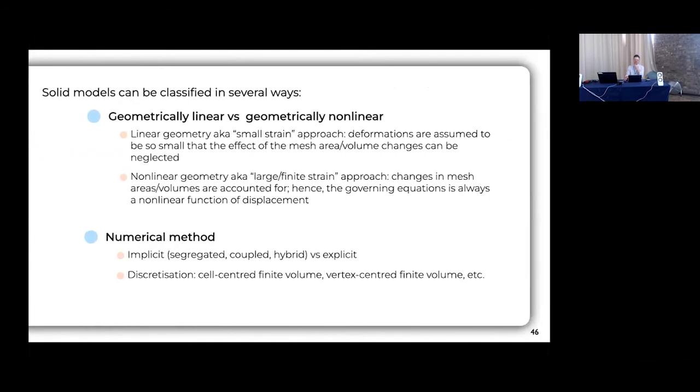Just to comment on, maybe you're solids people and you don't need to know this, but most of you are mostly from a fluids background. So in solids, let's say an analogy for compressible versus incompressible in fluids. In fluids, there's incompressible and compressible, where they're quite different approaches to solving a problem. You might just say, well, if everything's compressible, just use a compressible approach. But then you're like, well, that won't be efficient for an incompressible problem. So in solids, there's something called geometrically nonlinear and geometrically linear. So all problems are geometrically nonlinear.